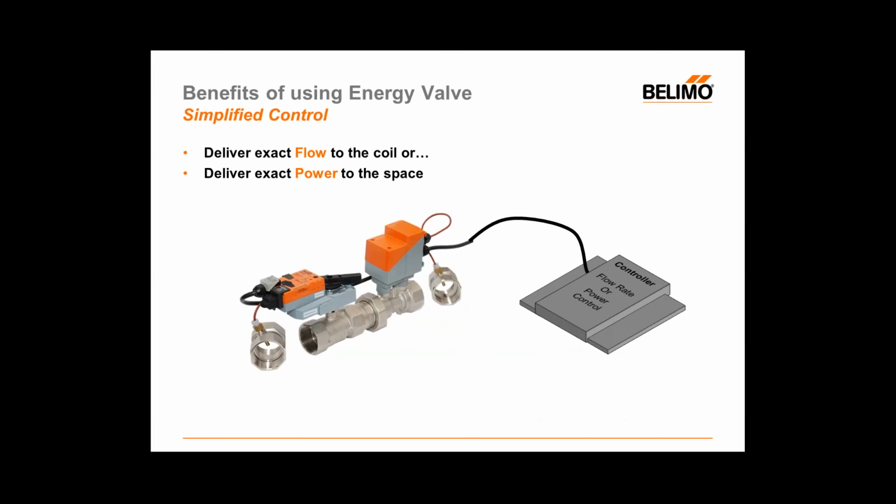How are we simplifying control? Well, an electronic pressure independent valve works a little bit differently than a standard mechanically pressure independent valve. An electronically pressure independent valve has a flow meter built into it, and it operates quite similarly to a pressure independent VAV system in that we're simply measuring the flow rate of the water, and we're going to modulate the opening of the valve to accommodate the flow requirement. So the signal from the automation system is interpreted as a specific number of GPMs, and the valve will simply modulate itself to find that number and stay at that number.